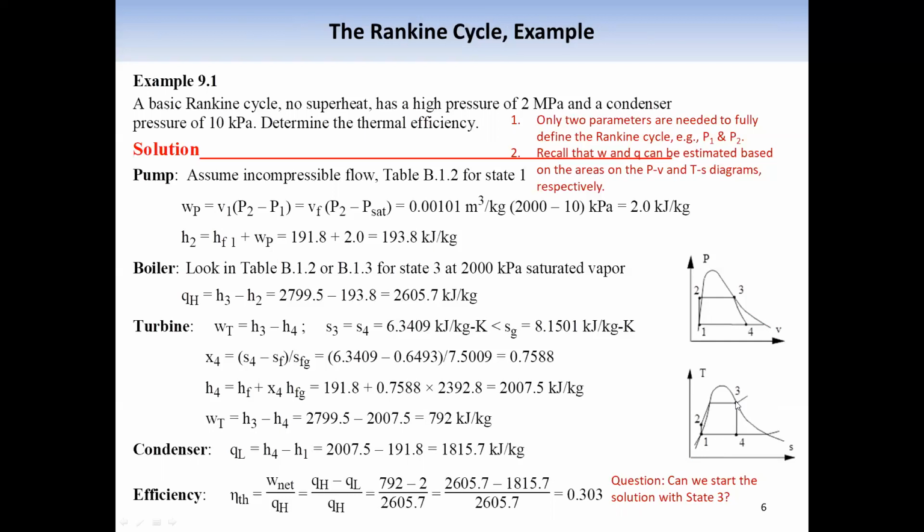For state 3, because we know the pressure is given in the problem statement, we can use the saturated vapor to calculate the temperature. This is on the saturation line. So temperature is known here too.